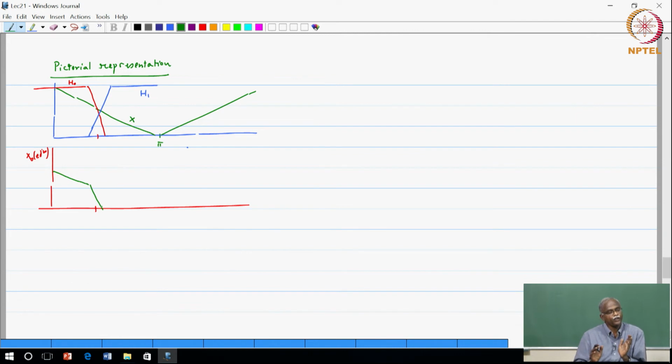That is the portion of the input that is captured by filter H naught, and it will have a copy on the other side at 2 pi. So, if you have this as 2 pi, then this is pi, and there is a copy of the signal which is a mirror image to this. So, make sure you draw it symmetrically, you can do it better than me.